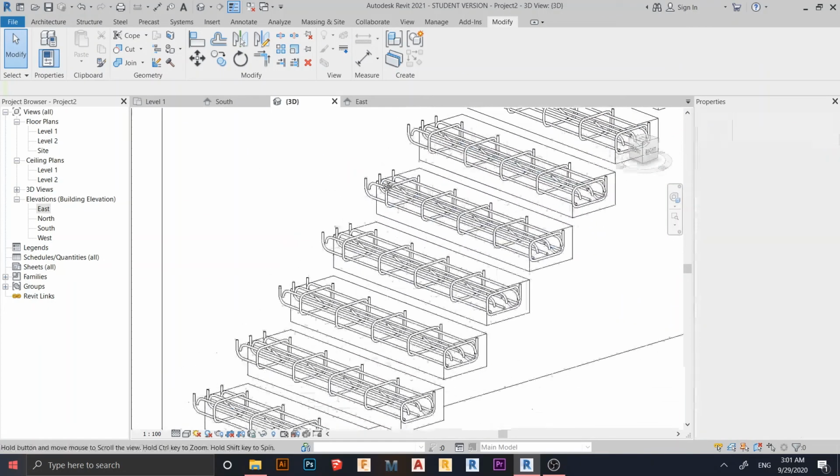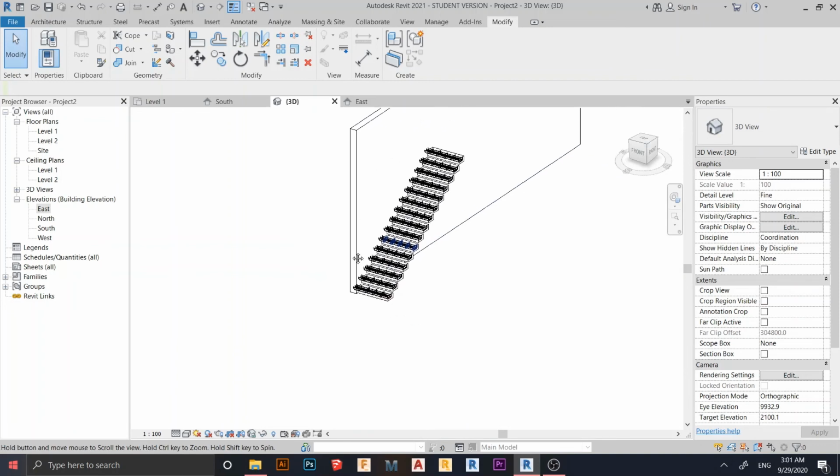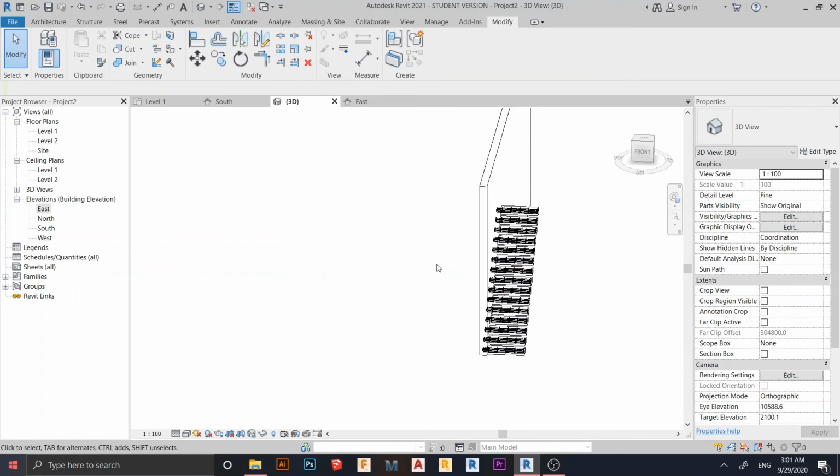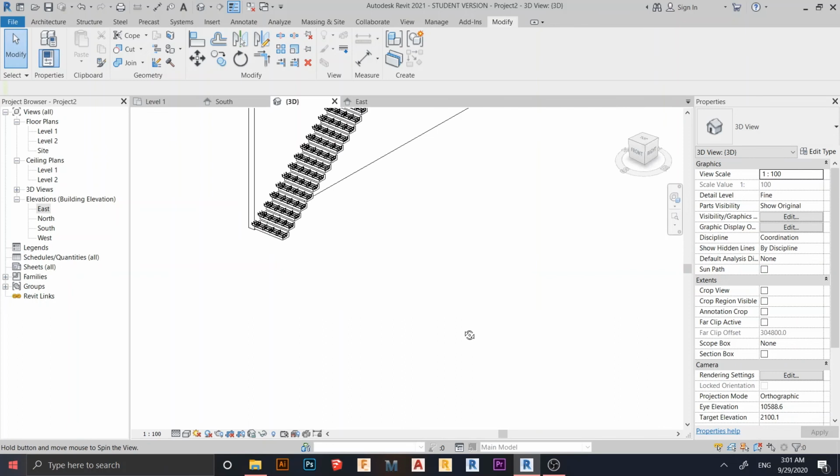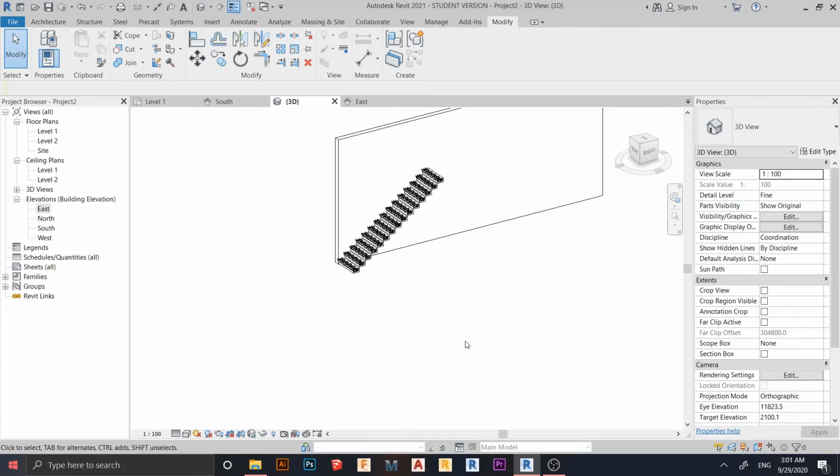As you can see, here is the connection from your shear wall, but this one I just played around with for the tutorial. Normally we use wood panel or steel for the connection from wall to our floating stair. But I want to make some reinforcement steel for you. I think it looks cool to use our rebar in Revit, because Revit is not a struggling way to create that. To create it in Revit, you don't need to buy a plugin for reinforcement rebar. If you know how to do that, it's very easy and saves your time.